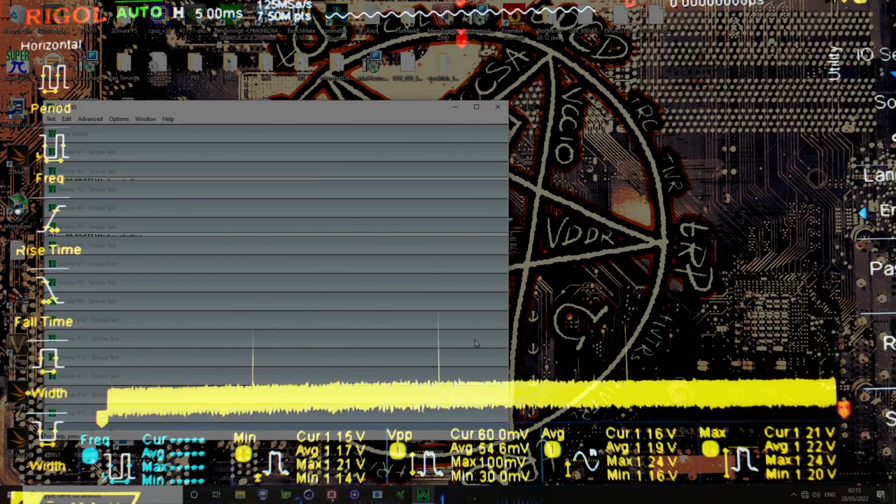Like, what's the point? Mode 1 to mode 2 to mode 3 is another 15, actually, it's not even 15 millivolts, it's 10. It's 10 millivolts going from mode 2 to mode 3, which is like, what's the point in having LLC settings that are right on top of each other like that? And then you go from mode 3 to 4, and it's another, like, 20 millivolts.